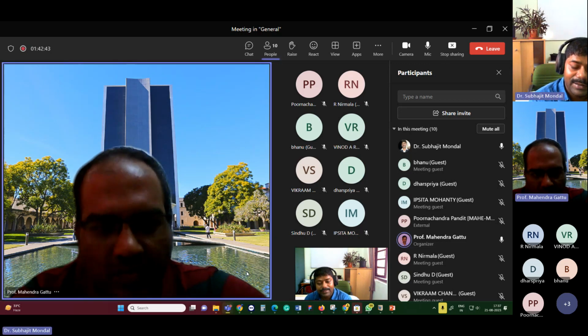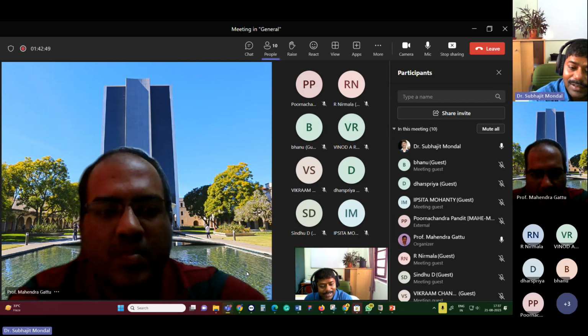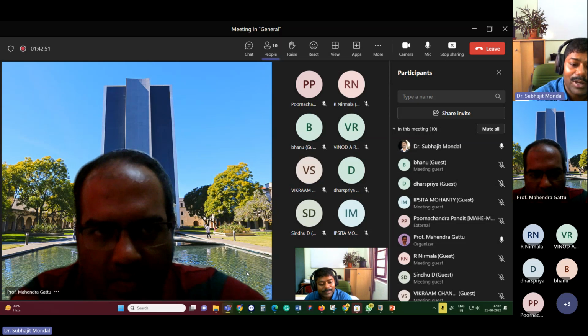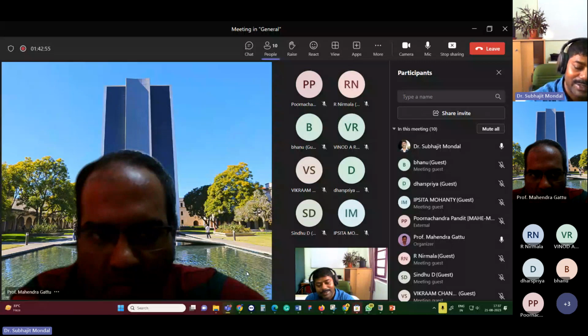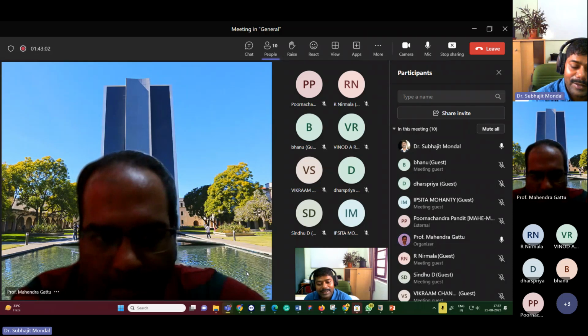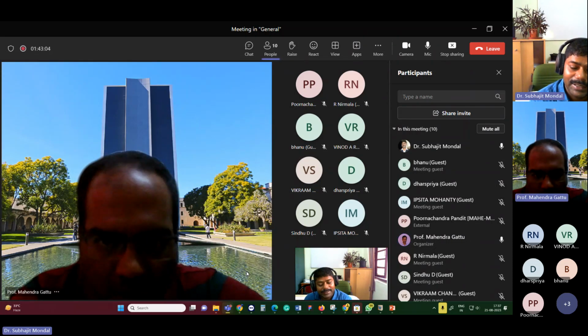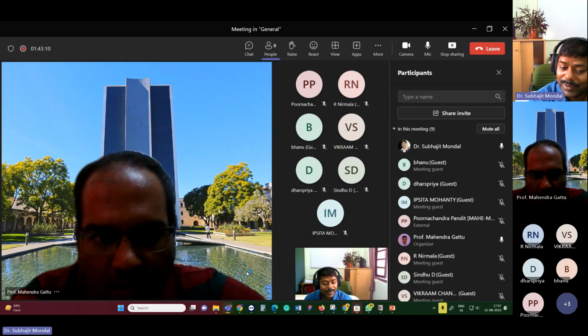So you have to see the position of the accelerometer from where you are measuring the response. When you say higher mode, you are talking about mode shapes. In terms of mode shapes, yes, it will be easy for you to identify the damage if you use a higher mode.